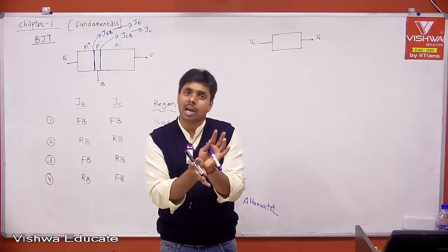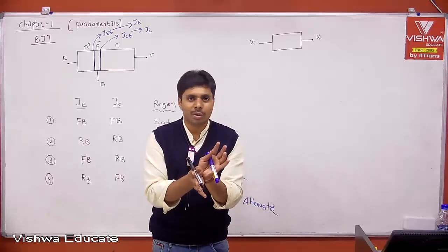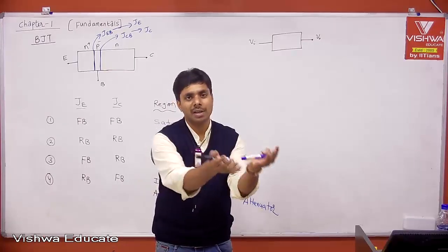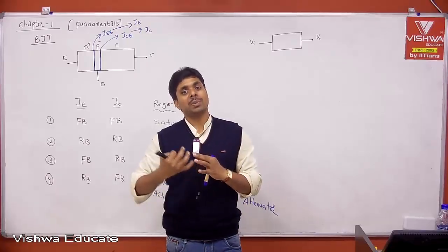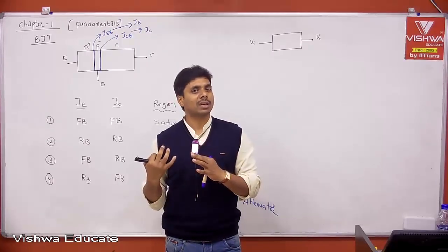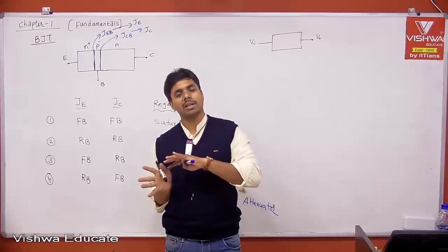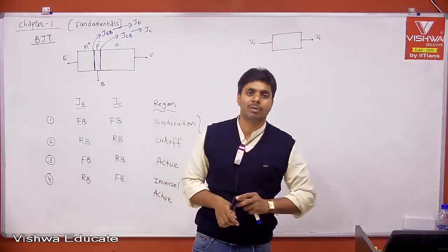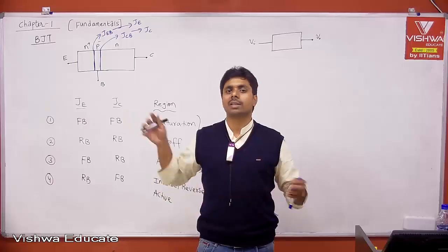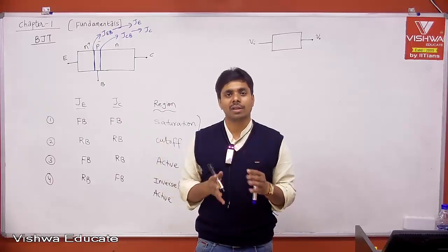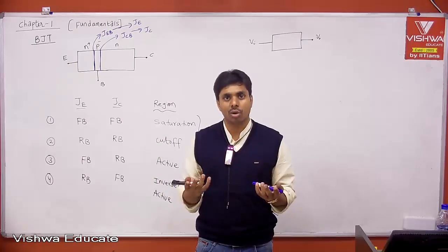But is it doing that continuously throughout its lifetime? No, because it already took energy from another source and stored it. It is not dissipating that energy like your resistor, but it gives the energy back. Therefore it is also a passive element, because over an infinite time period the net energy given by the inductor is zero.